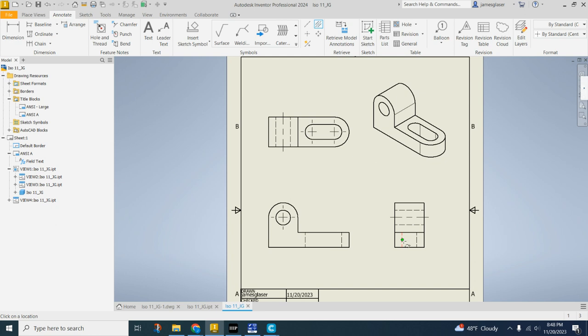I can do this here as well because I know that it shows up in exactly the center. But we're not going to dimension to those. You never dimension to hidden lines here like that, or these center lines that are here, but we just need to show that that's a center line to indicate that it's a curve.